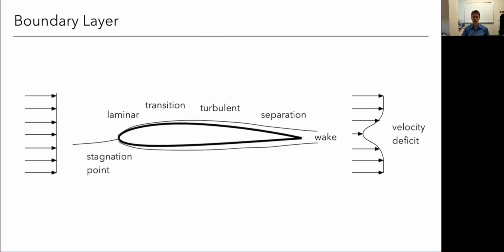So in potential flow theory, we could predict our forces and moments reasonably well, with the exception of drag. We get lift. In 3D, we can even get a side force, and we can get all three moments, pitching, yaw, and rolling moments, pretty well, as long, again, as we don't have big separation or separated flows. A wake is actually okay, as we'll see as we talk about lifting bodies soon, but separation is the problem. So as long as we don't have that, you get all those things pretty well, except for drag. And if you recall, for potential flow, the drag is always zero, which of course is not right.